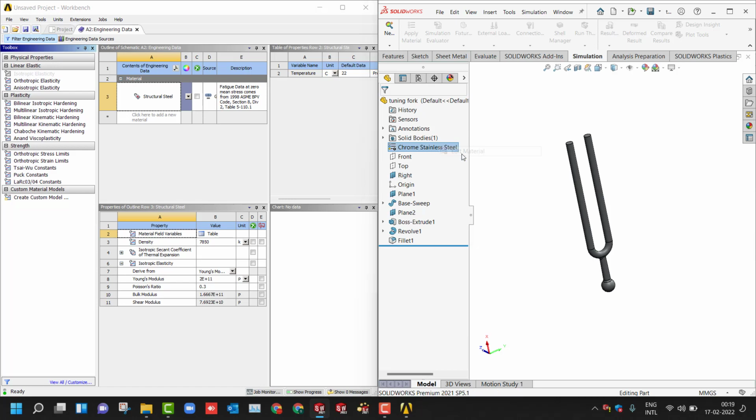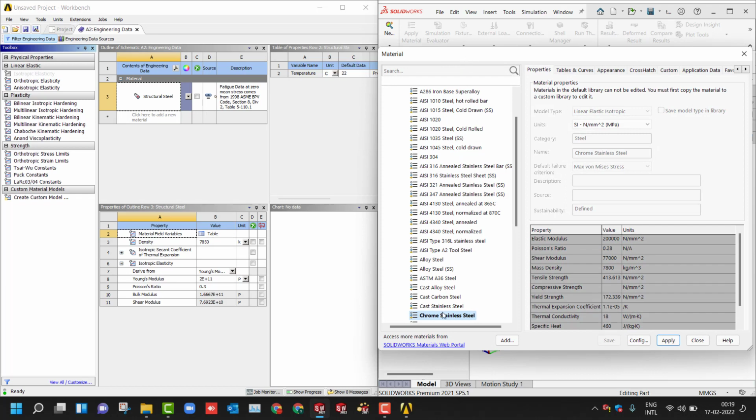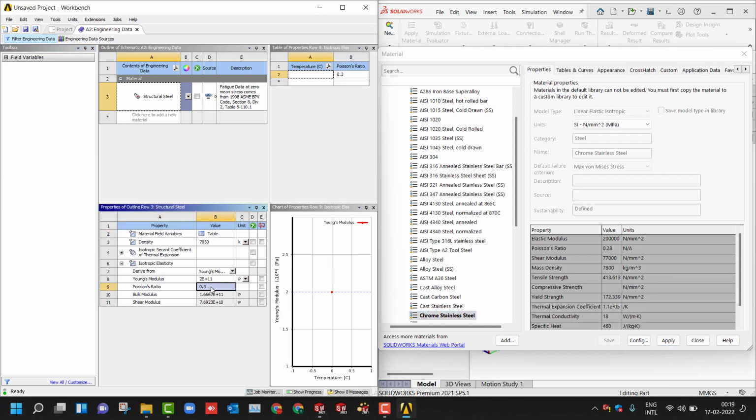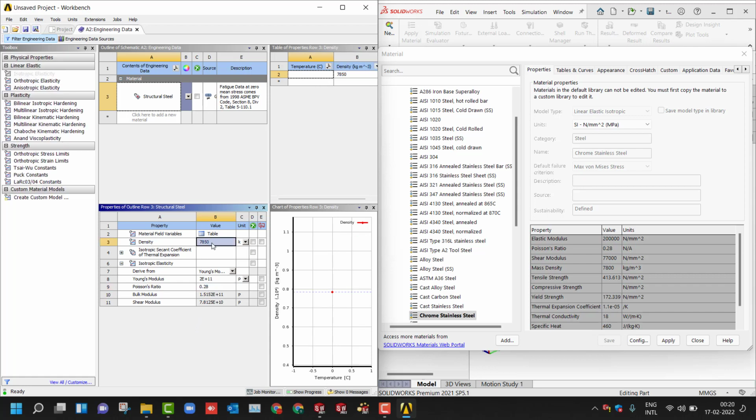So according to that, if I cross check the material properties here, I'll set the elastic modulus as 2 into 10^11, fine. The Poisson's ratio should be changed, so I'll make it 0.28 for now. Okay, and the density should be approximately 7800. I'm not considering other things for now, just to deal with this analysis of the frequency.